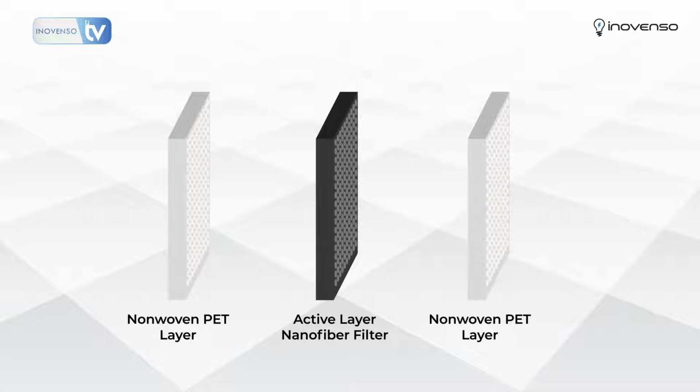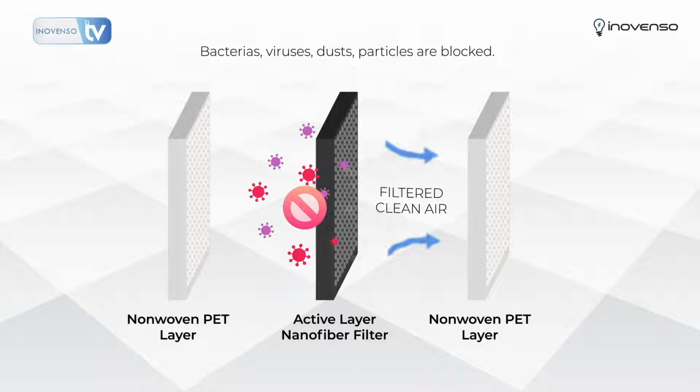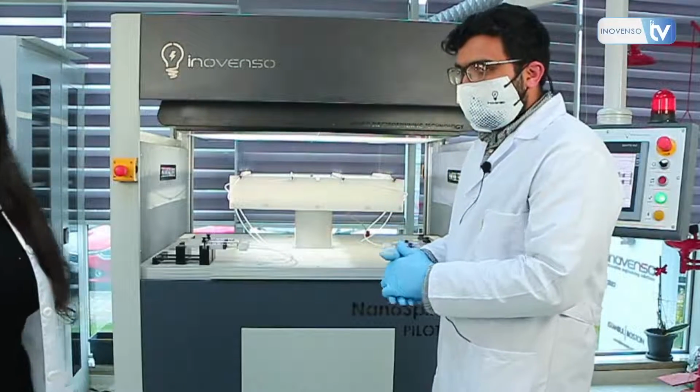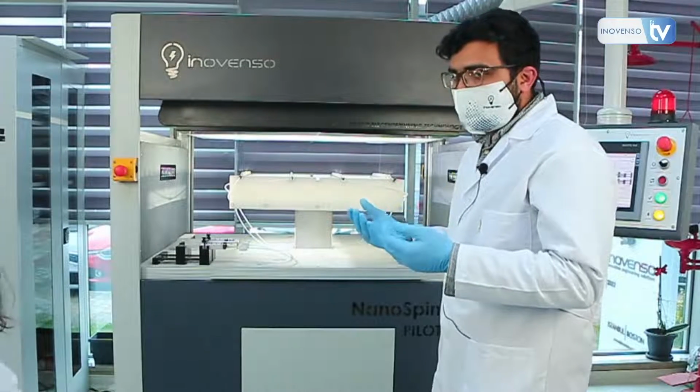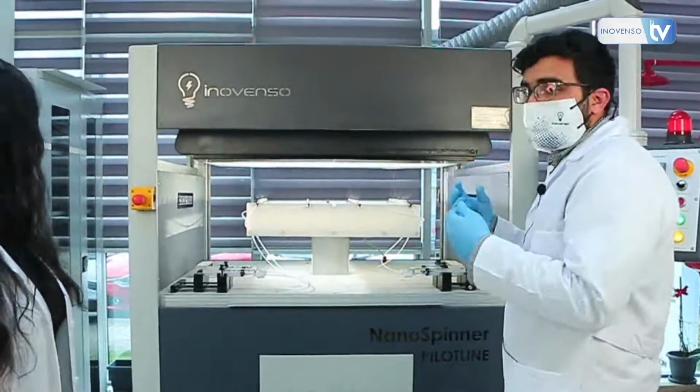Yeah, so we can move on, but we can also talk about what this filter media can produce. It depends, of course, on the thickness of the nanofiber layer. You can control the thickness in terms of GSM. Suppose you want N95 filtration media, you can coat the nanofiber to about 0.6 GSM for N95, and if you want N99, you can coat it to 0.8 GSM. It just depends on how much filtration efficiency you want.